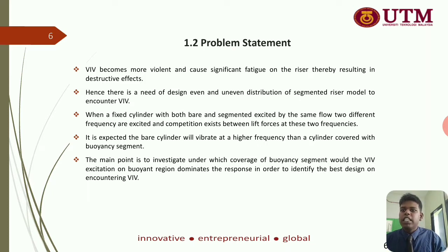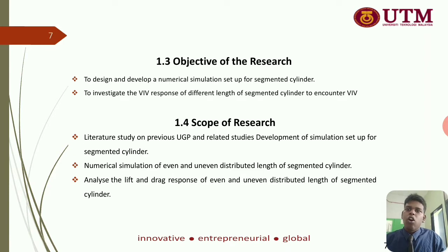Problem statement. The main point in the problem statement is to investigate under which coverage of buoyancy segment would the VIV excitation on buoyant region dominates the response in order to identify the best design on encountering VIV. Objective of research: to design and develop a numerical simulation setup for segmented cylinder to investigate the VIV response of different length of segmented cylinder to encounter VIV.